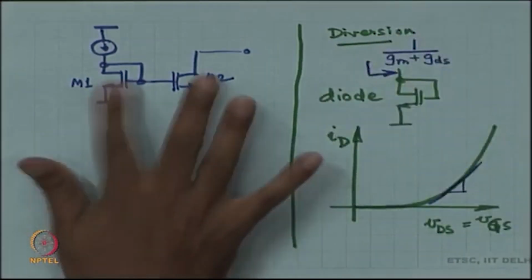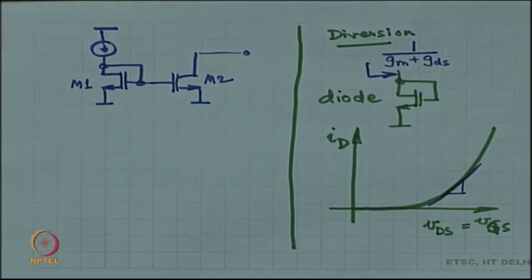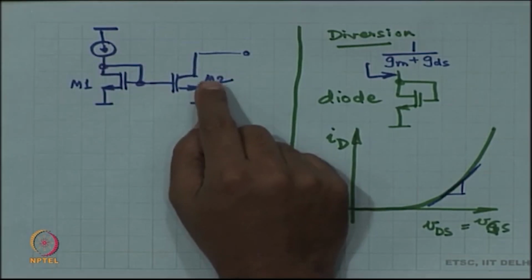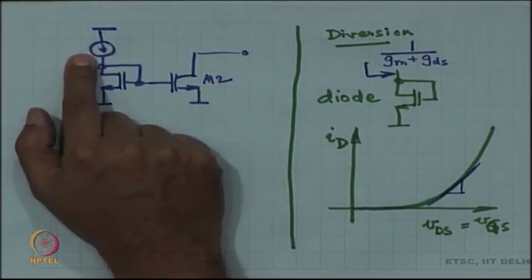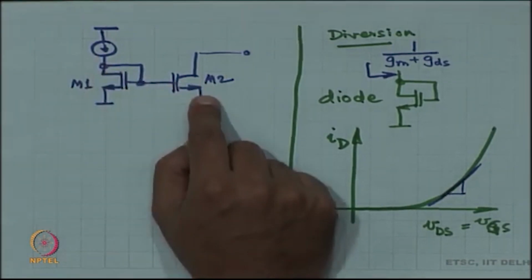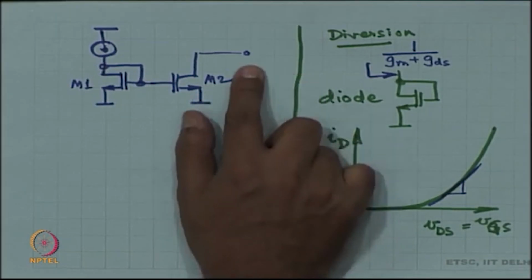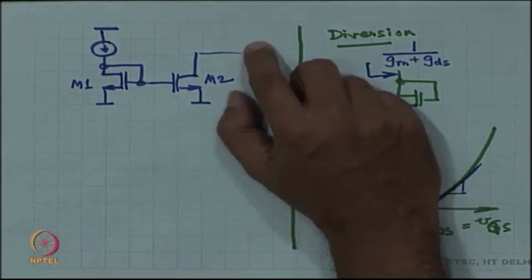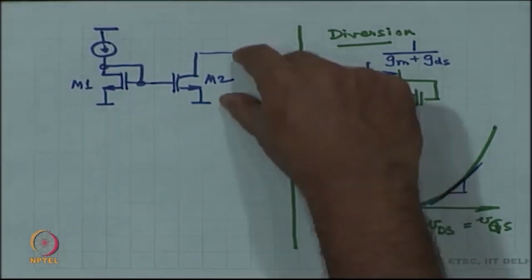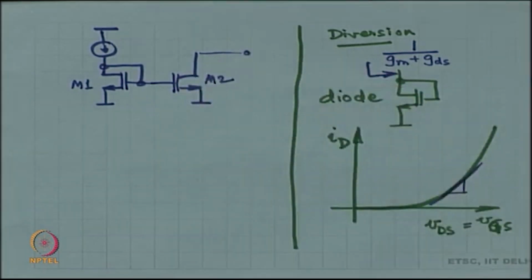All right. So, getting back to our current mirror circuit. So, we looked at two things. Number one we looked at was value. The value is obtained from the reference. Number two we looked at is the output impedance. The output impedance of this is nothing but RDS. Okay. Number 3 is, what is the set of voltages for which M2 remains in saturation and the device actually works like a current source.